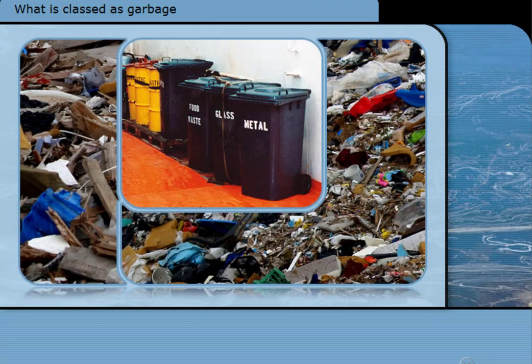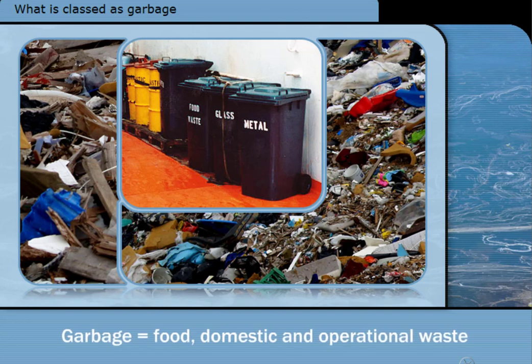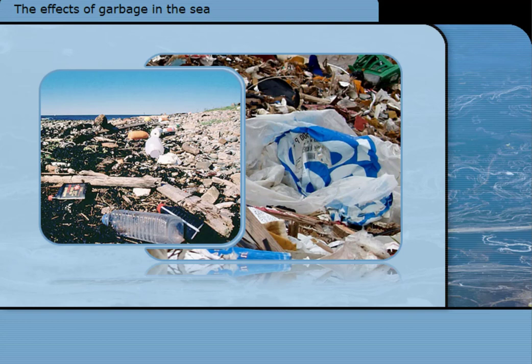Annex 5 of MARPOL defines garbage as all kinds of food, domestic and operational waste, excluding fresh fish, generated during the normal operation of the ship, whether disposed of continuously or at intervals. Plastics, cooking oil, fishing gear, animal carcasses and cargo residues are among those substances specifically defined as garbage by Annex 5. Cargo residues and slurries, such as those produced by hold washing, are classed as garbage, except where they are substances listed under the other annexes to MARPOL. Deck wash water is also considered as garbage. Plastic presents the greatest danger to marine life because of the time it takes to break down.